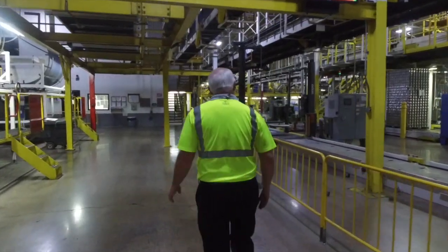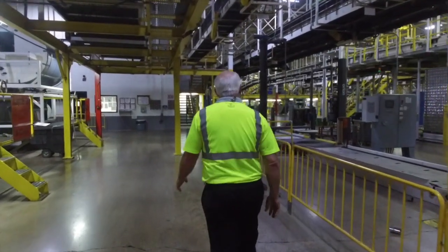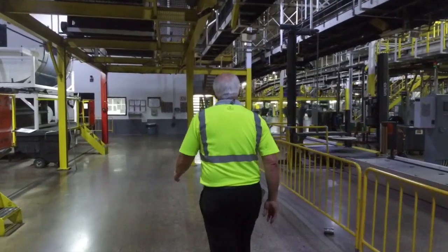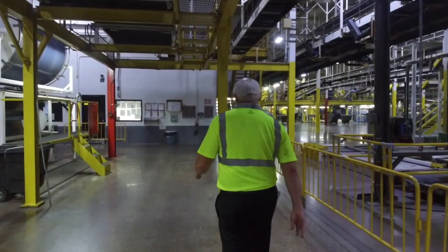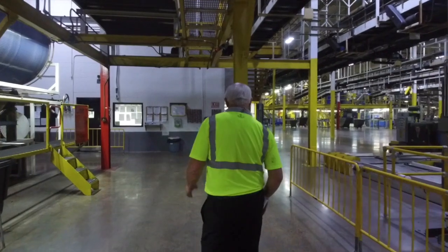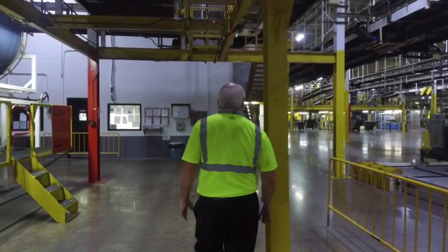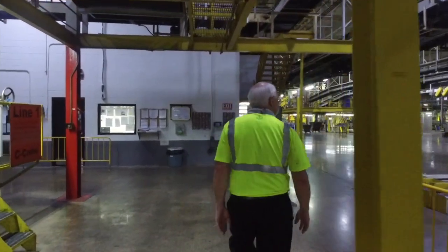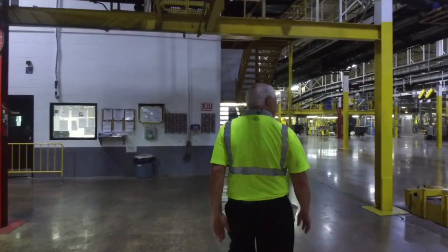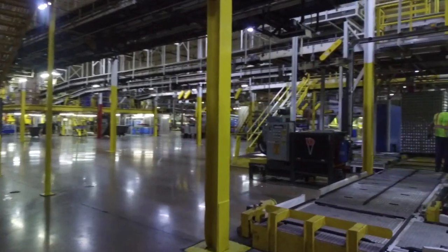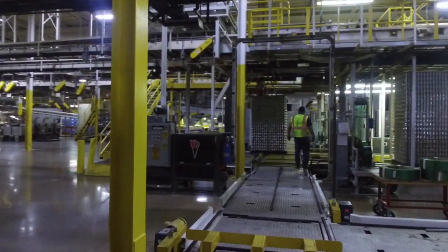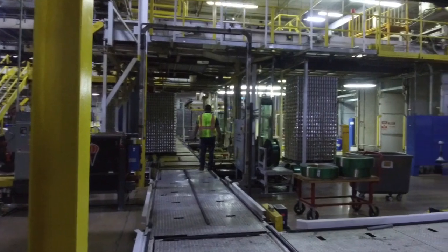Next is the biggest headache anybody has with compressed air: leaks. Air under pressure tends to leak, so constant vigilance is needed to find and fix leaks. This may seem tedious, but managing leaks can lead to large savings as leaks waste 20 to 30% of generated compressed air. When you're visiting a plant, ask if they have a program to continuously find and fix air leaks. If they don't, tell them that it's a good idea to outsource compressed air system maintenance to a third-party service.